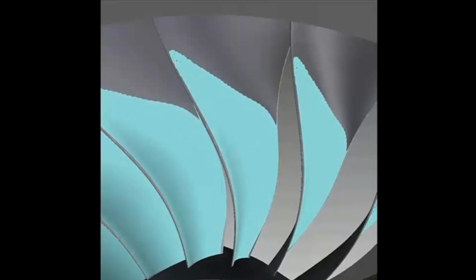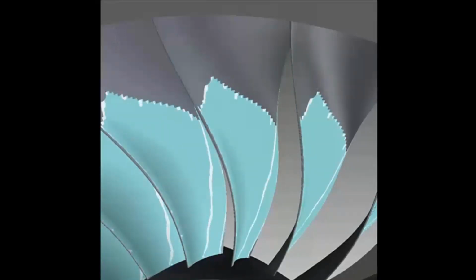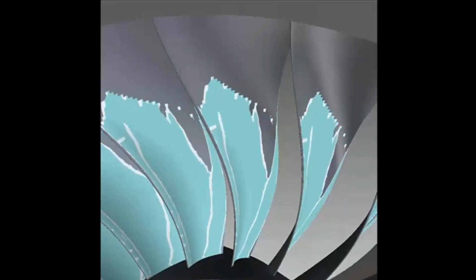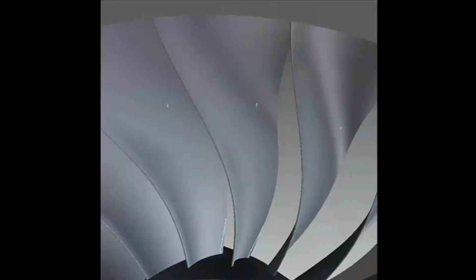This feature allows you to easily generate animations to predict mass of accreted ice shed due to rotational and aerodynamic forces, account for surface adhesion, mechanical stresses, and crack propagation in accreted ice. This concludes our demonstration on how to use FENSAP-ICE's ice shedding feature to simulate cracking and shedding of ice due to rotational forces.